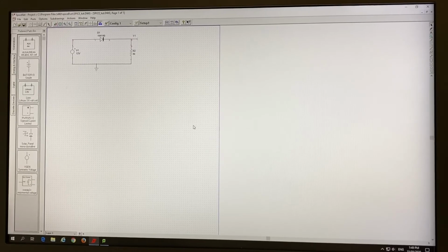So the diode is actually used for rectification purposes. If you have done power electronic converters, or just before power electronic converters, you have seen a bridge rectifier or half-wave rectifier. If you connect one diode the way you connect it, and we assume that our resistor, R24K in this case, is the load, and we give an AC signal, we can do a rectification. Rectification is just changing from an AC signal to a DC signal.